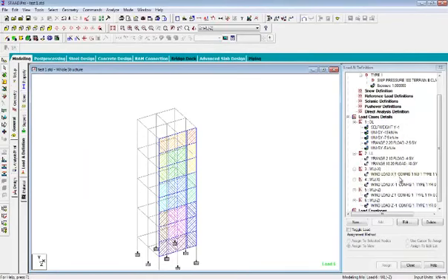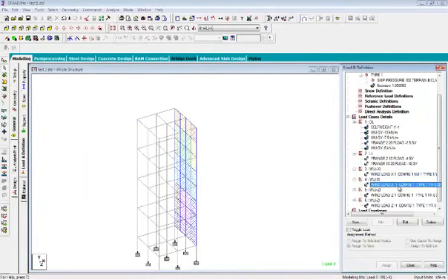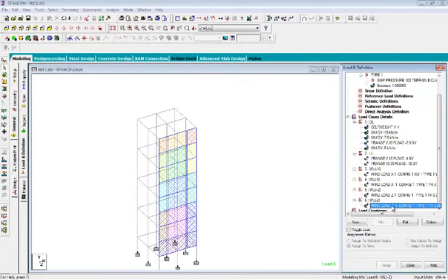So in this way we have added the wind load with exposure 1 in all directions: plus x, plus y, minus x, plus z, minus z. In this way, let the wind come from any direction, it will be registered by our structure. But say I am living at a place where the wind direction is only from plus x and plus y, meaning from east to west only.